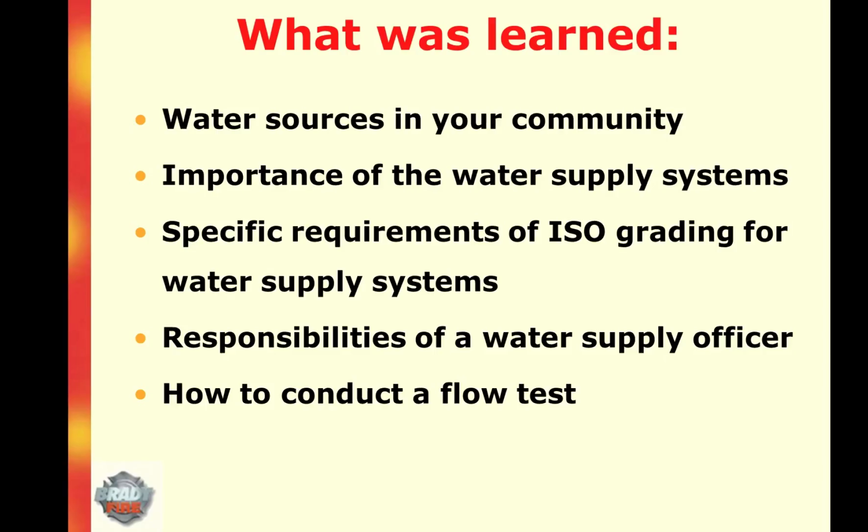To conduct a proper flow test, you need to have the proper tools. The outlet type determines the proper coefficient of discharge. The outlet cap pressure gauge goes on the flow hydrant first to record the static pressure. Then you relocate the cap gauge on the residual test hydrant to make sure you have at least a 25% or 15 psi drop in pressure to validate your test.